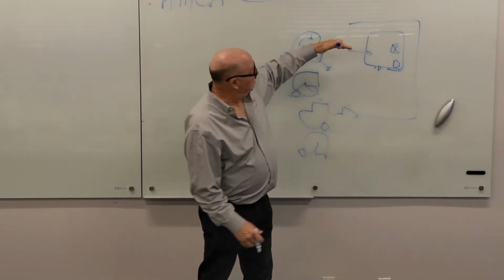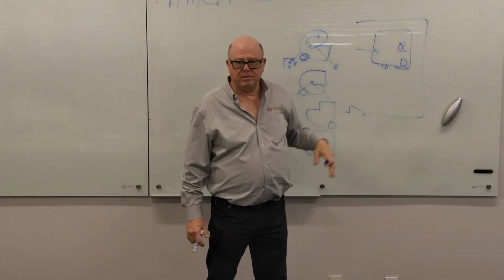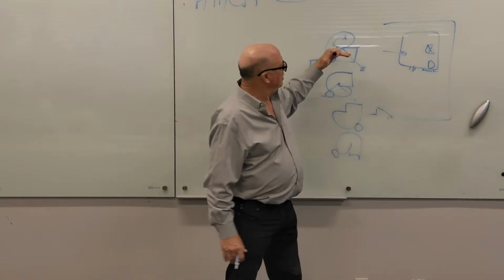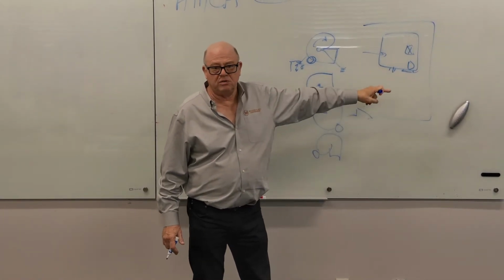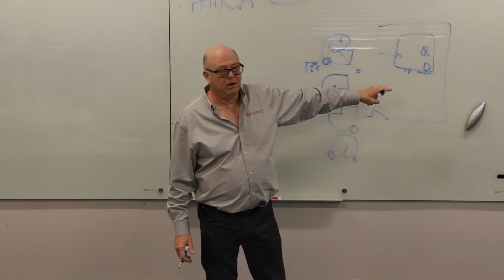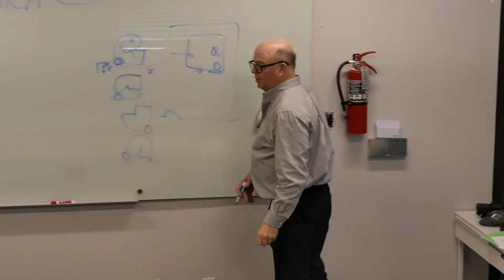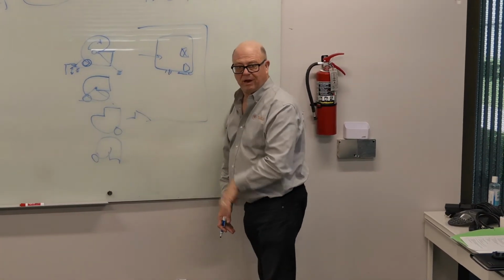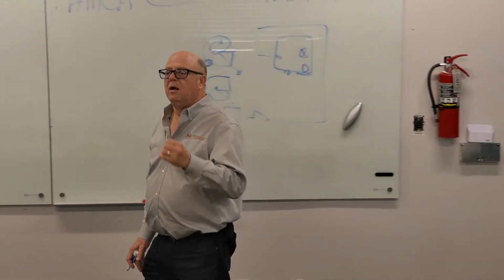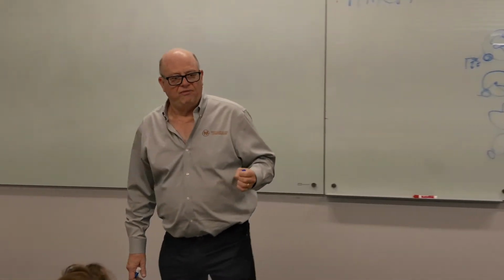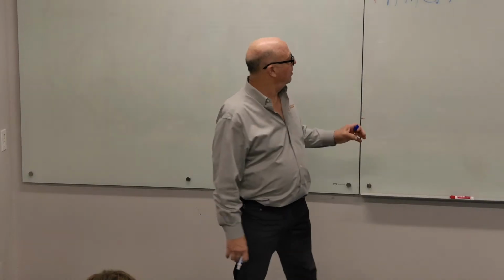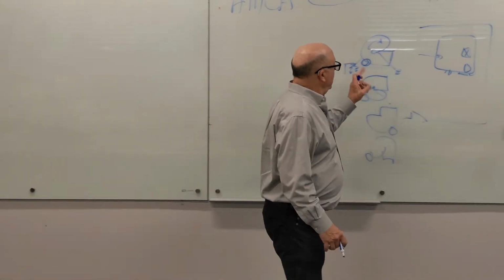And so, if it's a Carrier, or my memory is a York, that would be right hand. If that's Trane, it's a left hand. Because now you're standing here with it blowing in your face, okay? That is a point you don't ever want to foul up. So we've talked about that. Now,